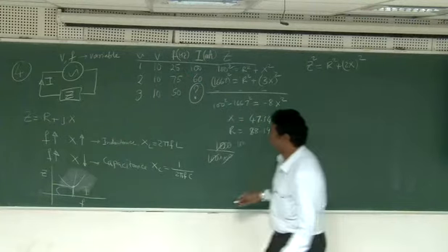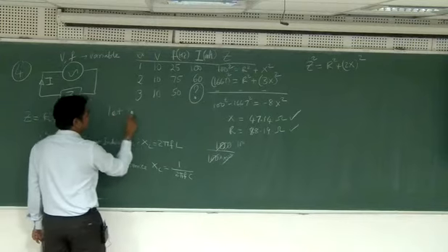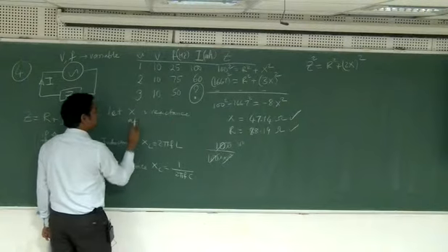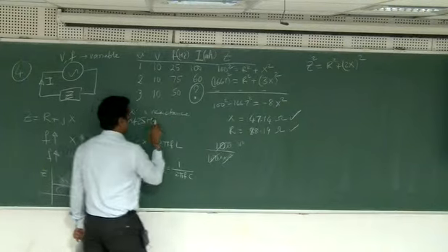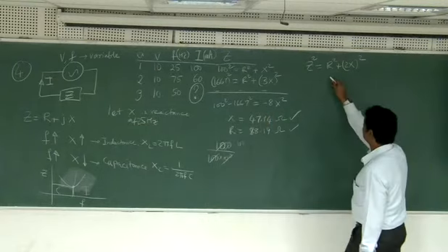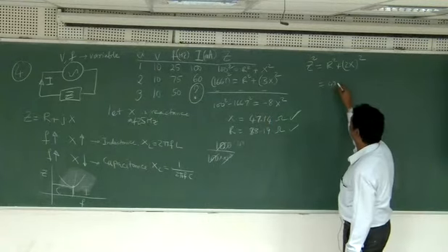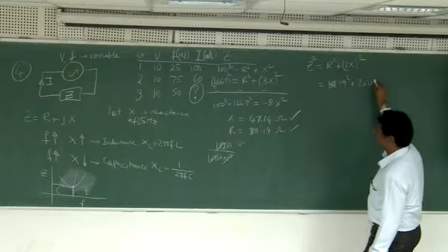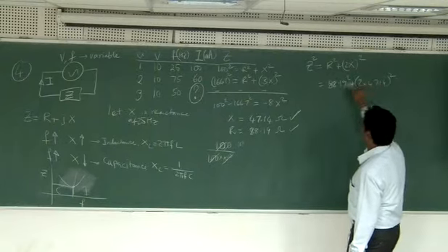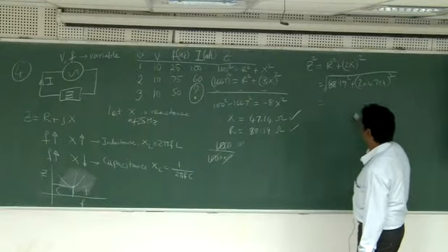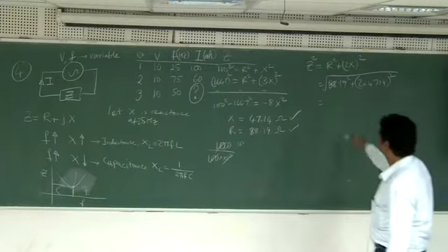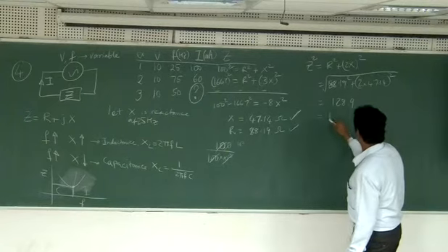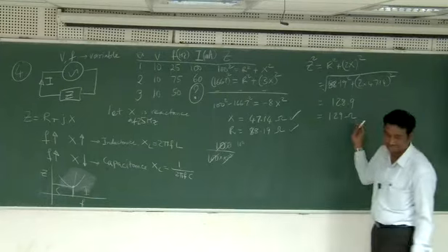Okay. So maybe I'll just write it. Let x is reactance at 25 hertz. So in this case, I know R and I know x, that is 88.19 square plus 2 into 47.14 whole square, and then under root. So this will be my new impedance. How much will it be? Okay, 128.9. Have you already calculated it? Cool. So let's write it 129, just rounding off.